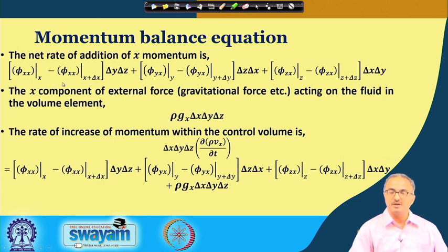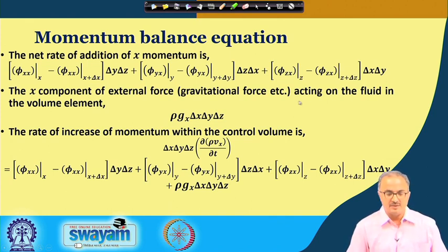Here we have the equation, and we are writing in the momentum going in, and these are the terms which are momentum coming out of the system. And these forces, let us say that we take the body force as a gravitational force. So, we are writing it in terms of some g, but it should be understood that this represents in general a body force. It could be anything; gravity is one of the body forces. And this is also per unit volume.